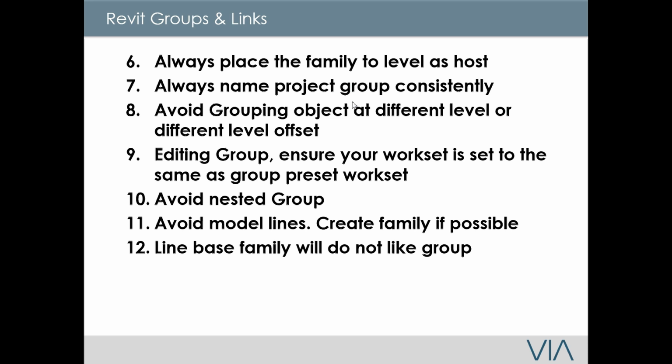Okay, the ninth is another pet peeve. When you're editing groups, ensure your workset is set to the same as the group's preset workset. What I mean by this is that if you have set your group to, let's say, a furniture workset, and now when you're working on the project you're using Workset 1, then every element you add into the group is going to have Workset 1 rather than the furniture workset.